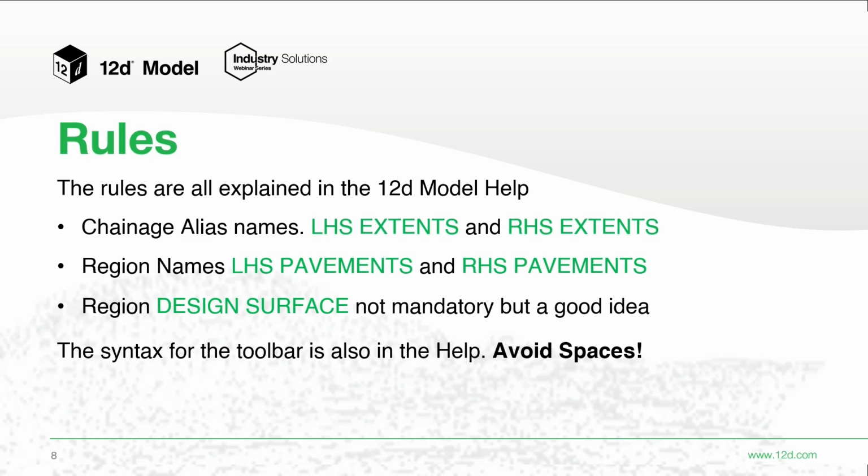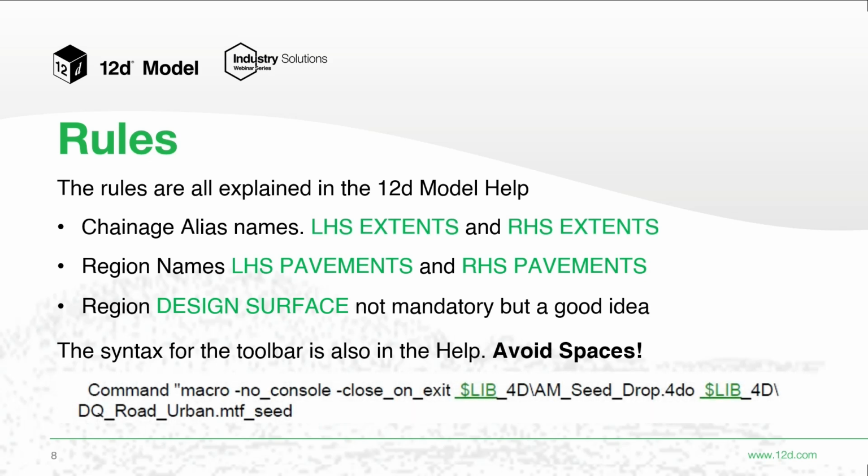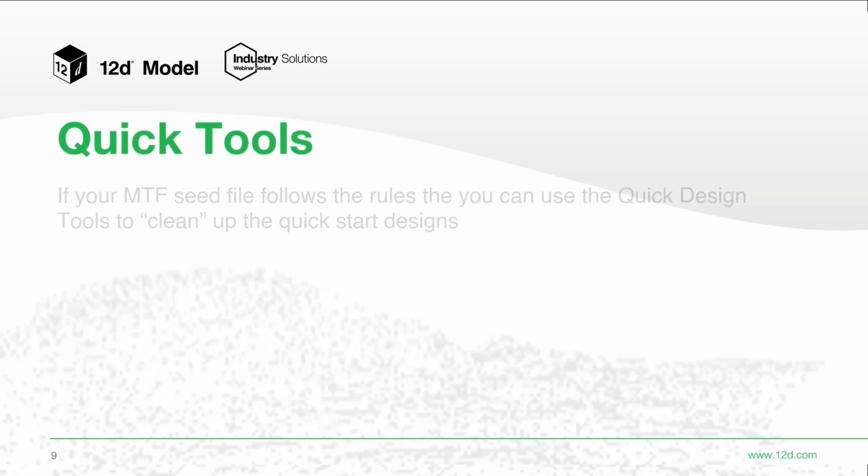So if you want to create your own one button toolbar, say I want to do a retaining wall, or a stop bank or something like that, then you can make your own toolbars, and it's pretty easy, and that's also described in the help. Just one thing: in your names for your seed files, avoid at all costs having spaces, because then the command inside the toolbar will have to be within speech marks and have a couple of very prescriptive backslashes put within the name. So if you can avoid spaces in both your path name and your seed file name, it's going to help out a lot.